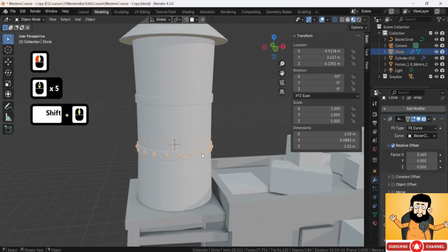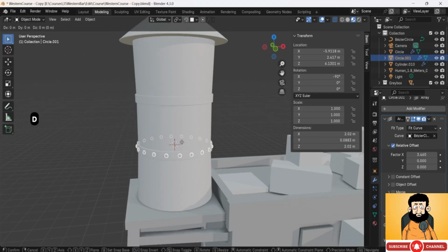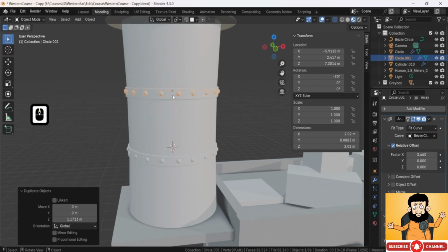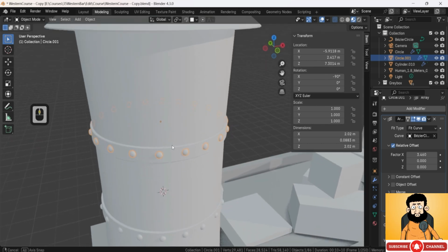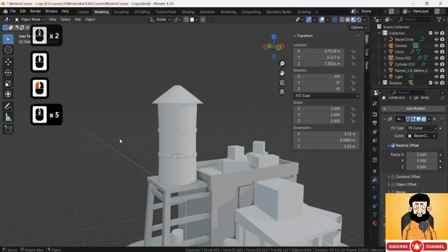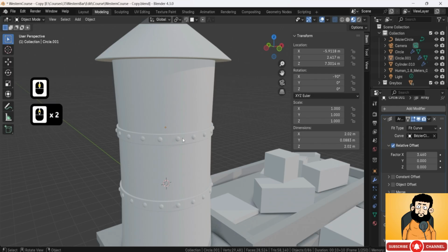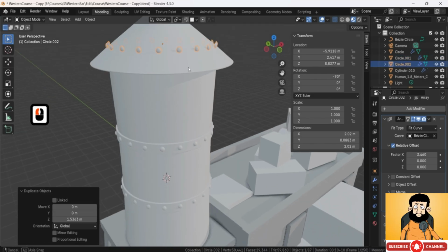All right. The other thing that we need to do is probably going to be just duplicating it upwards. So I'm going to click Shift D, GZ, move this upwards. I'm not too worried about the gizmo over here because it only starts acting up whenever we offset it from the center point. But right now, in regards to Z value, it's going to be still kept to that nice deformer going all the way around. So that's quite nice for us. I'm quite happy with this. We only need to think about this last piece going upwards. So I'm going to again select this, click Shift D, GZ, move this upwards like so.